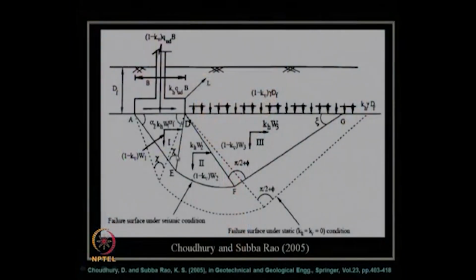So, this is the analysis. You can see over here, this is the line diagram of a cross section of a shallow isolated strip footing. This is the width of the footing B, this is the depth of embedment of the shallow footing Df, and as per Terzaghi's definition, if it is a shallow footing, then this ratio of Df by B should be less than or equal to 1, and this is the length of the footing. This length has been considered much larger than the width of the footing, so that we consider it as a strip footing for the analysis.